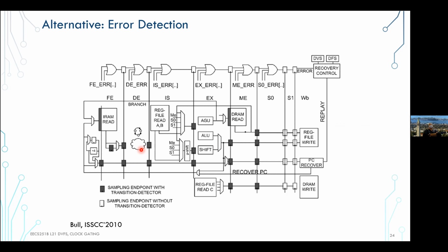Exactly. That's exactly right. So you first drop the frequency, you give yourself slack. And the next thing, you are basically changing the voltage to fill that slack, right? And of course, you need to make sure that your frequency step versus your voltage step is not such that, when you make, let's say, a reduction by 1 notch in frequency, your voltage step kind of goes over, right? So you have to make sure that that's true.